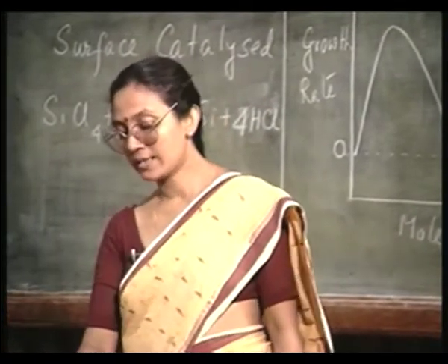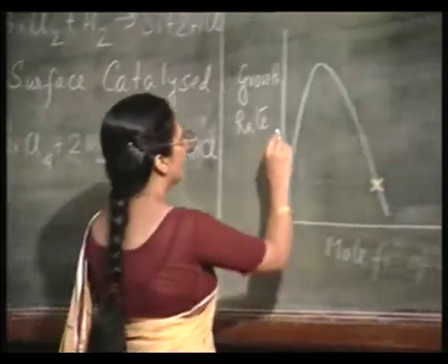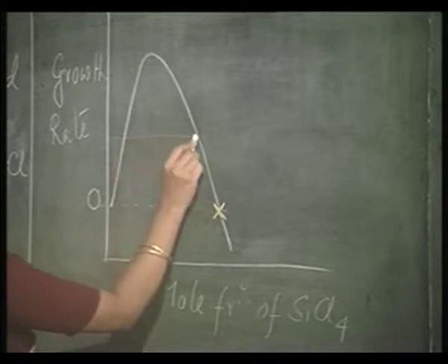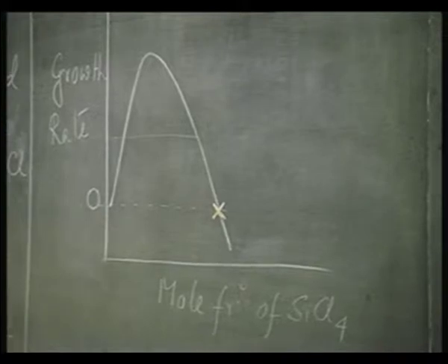The other interesting thing to notice is that as you increase the growth rate, the epitaxial layer is no longer going to be single crystal.